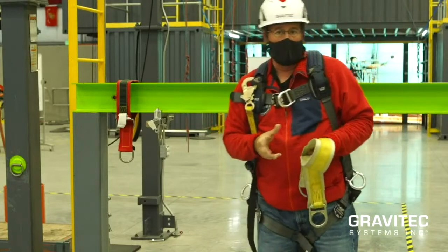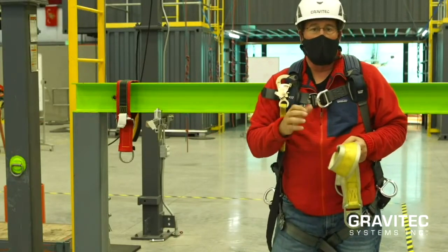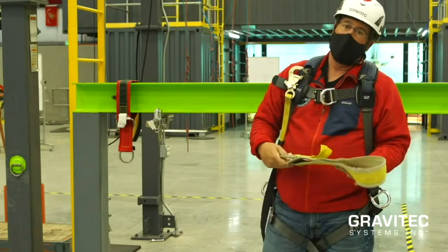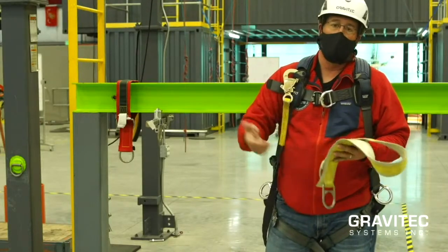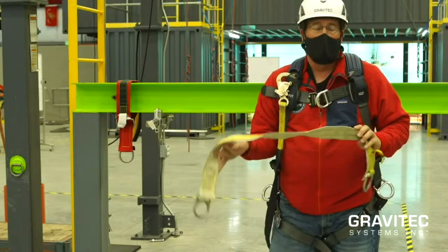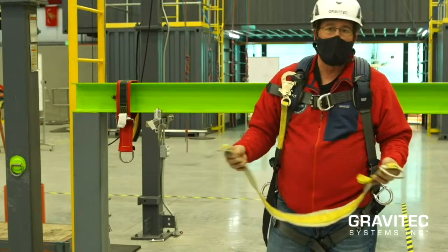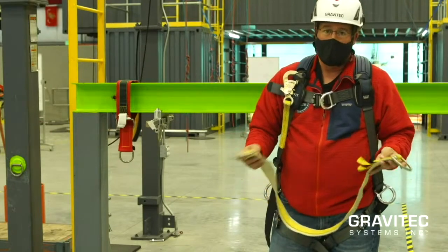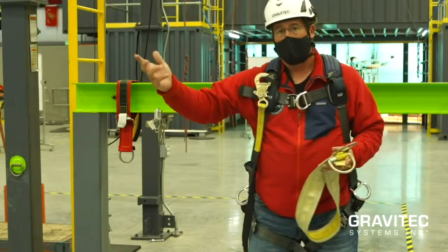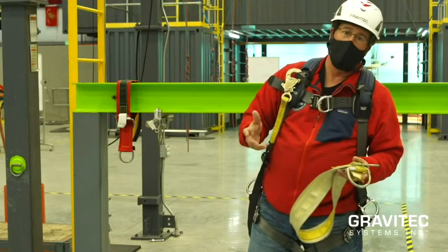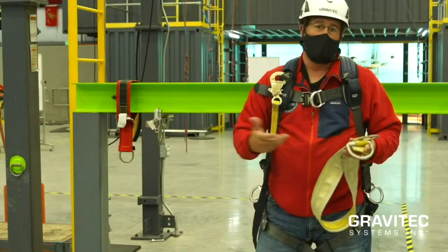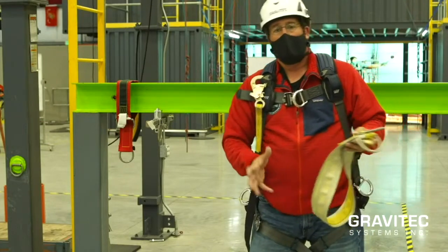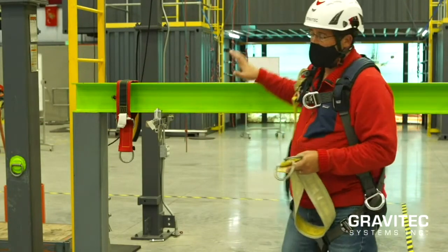I'm not going to spend a whole lot of time this afternoon on the anchorage connector, okay? Generally speaking, you don't have to pay a whole lot of attention to the anchorage connector, at least in regards to quality, because a manufacturer designs it, specifies the material, and tests it. Generally speaking, everything's 5,000 pounds. They label it, they supply the instructions. If you have a problem with an anchorage connector, chances are you just have a purchasing problem. So you can go out and find whatever type of anchorage connector is going to be compatible with your anchorage.